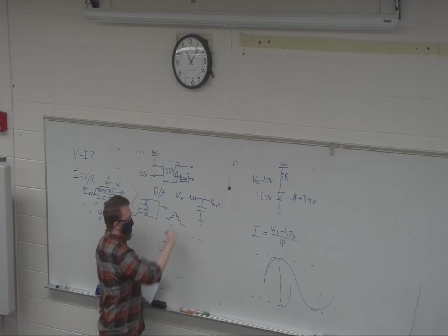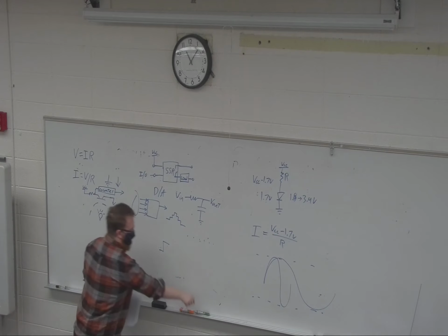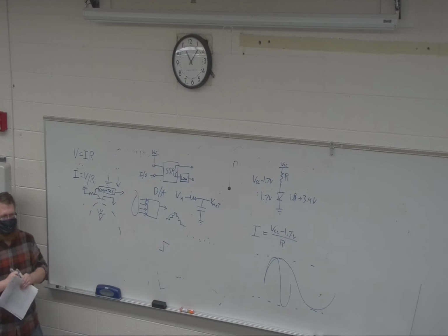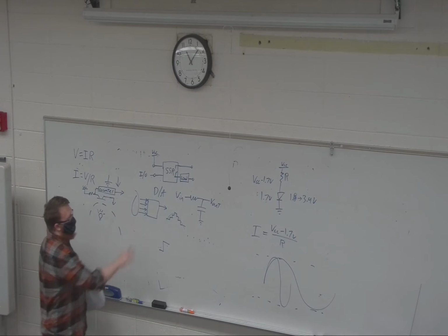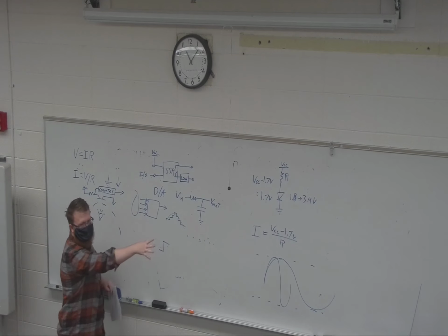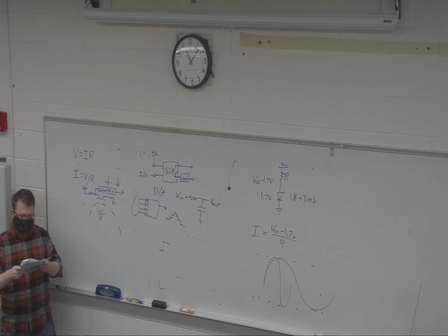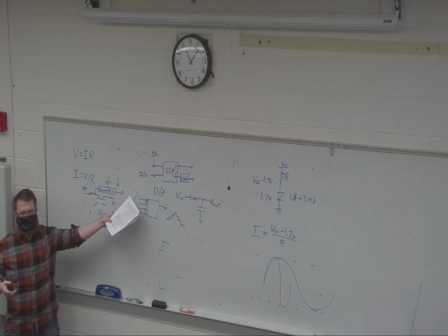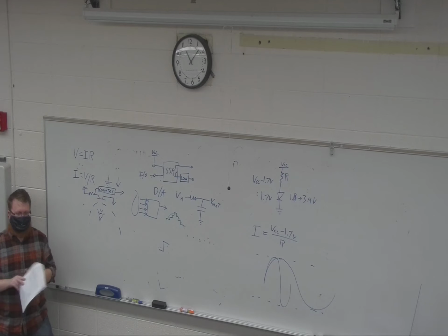So this gets rid of high frequency components, and so instead of looking like this staircase, the output of that will look more like that. It's kind of like an averaging filter. So with this D to A, in output levels, a lot of times you'll filter it to make it look a little bit smoother, and that's how you interact with the real world. It's common, again, this is drawn as a 4-bit, to have 8 to 16. I think I've seen as high as 24 or even 30, but it gets really hard after that.